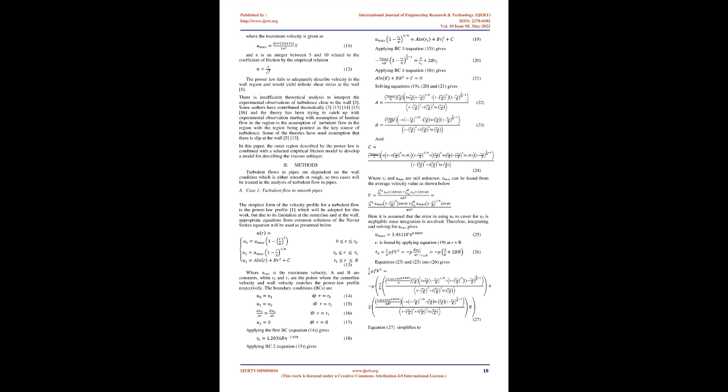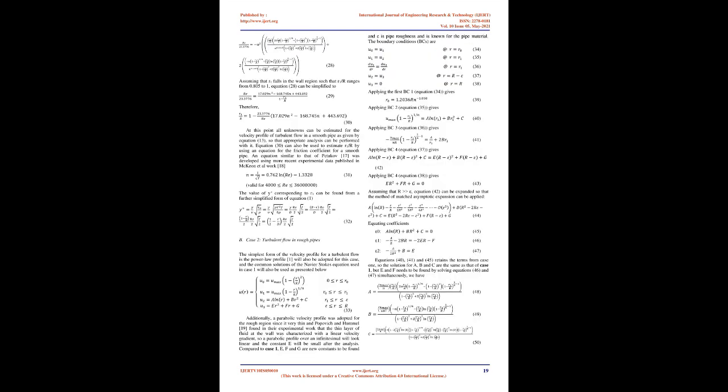The wall shear stress τ0 can also be found using the coefficient of friction, with the equation. Specifically, the velocity profile of the viscous sublayer determines the wall shear stress τ0, which is an important parameter for describing turbulent flows too. In experiments, it is not easy to obtain accurate velocity measurements within the viscous sublayer, though there is a wealth of data, where v is the average velocity.